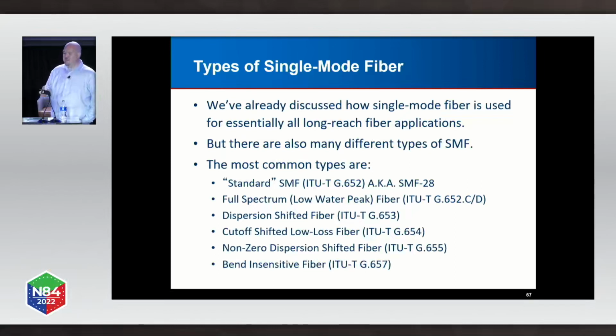So then there's G.654, which is the fiber that's for subsea stuff. Then after they figured out that 653 was a terrible idea that should never have been done, they were like, oh crap, revert. So they came up with non-zero dispersion shifted fiber, which is similar, but you don't get that point of zero. So it turns out we actually like dispersion. We need dispersion. Dispersion is important. But when this was originally designed, people didn't know that.